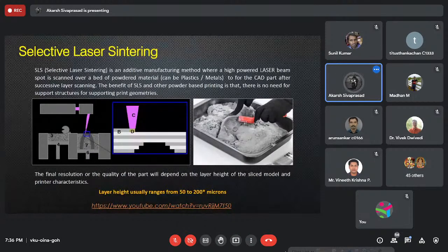The laser they use is really, really powerful, usually in kilowatts. And one important problem about this is that generally the laser is focused on one specific point, usually the center of the platform. But when your galvanometer scans it to the extreme corners, you tend to distort the beam.